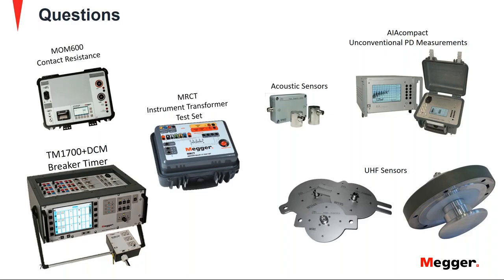And the issue, if you do have an interruption by circuit breaker or disconnector between your partial discharge source and UHF sensor, typically you're using multiple UHF sensors, as we saw, in different areas of your GIS. Now, you may have an interruption on one sensor, but you should be able to pick something up on another sensor, which should give you a relative idea that the partial discharge is over in that area. And the beauty of these UHF sensors is you have multiple, whether they be internal or embedded, where you can move to another sensor within the GIS, or if you have the external flange sensor or window sensor, you can move to another area in which you have the ability to apply that UHF sensor where you are getting a signal, and you can basically track down that partial discharge source.